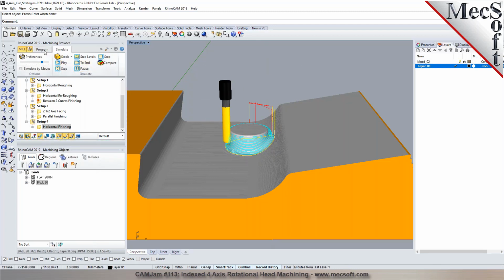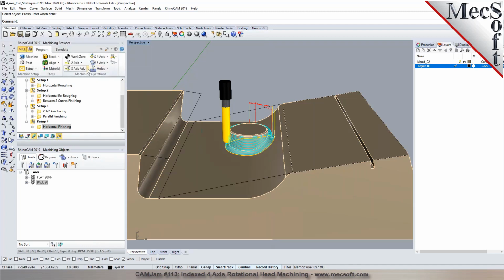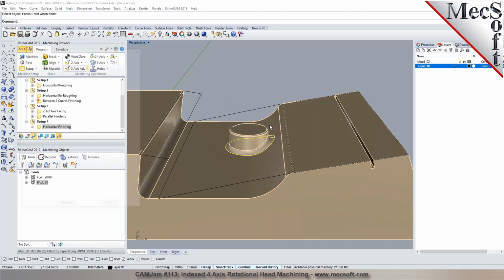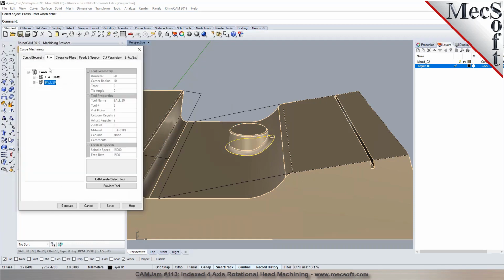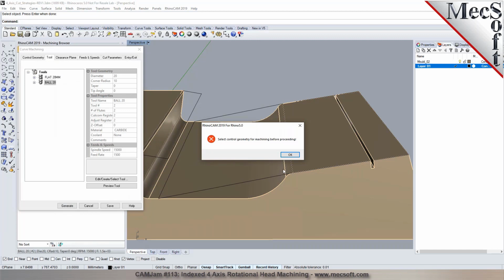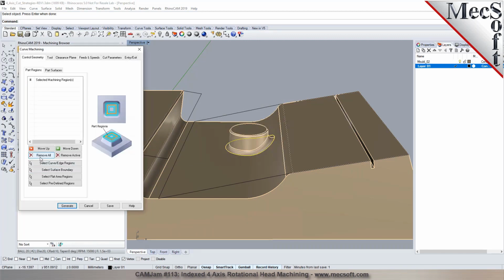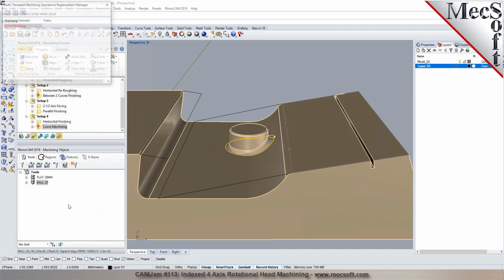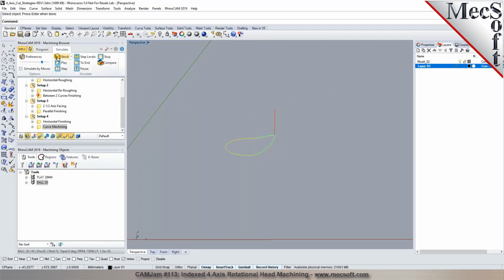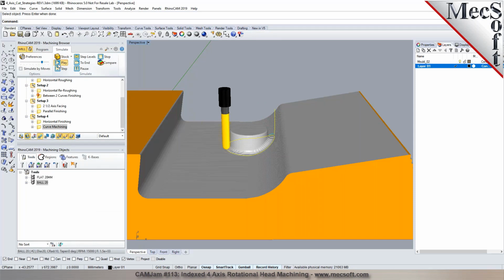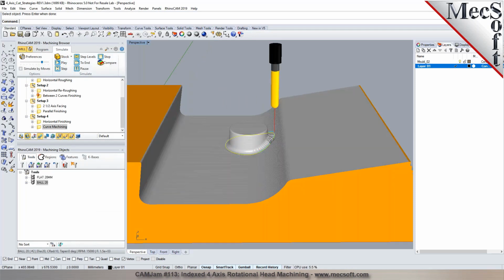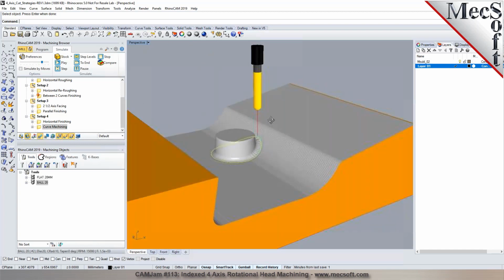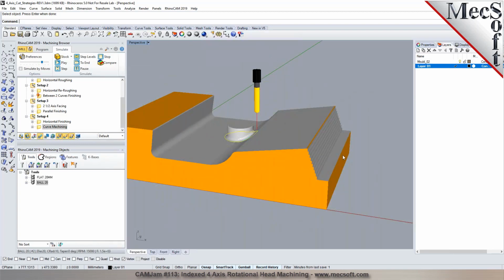And you can go back and clean this up with a 3-axis operation like a curve machining. So just to go around to clean it up. Go around the edge. Yep. So select my control geometry. So I'm just going to go pick this here. And if the radius is matching exactly what you have, it will just give you one nice pass to go clean it up. Yep. Or if you want to do additional passes, we can step it over as well. Yep. That demonstrates. All right.